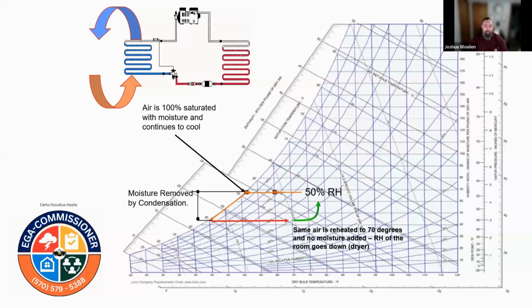And then what I did here was show you the value of moisture removal by condensation during drying, and how it refers to the amount of water vapor converted into a liquid and subsequently removed from that environment. This process is crucial in structural drying, as it helps to reduce the overall moisture content in the building materials, preventing issues like we discussed: wood damage, mold growth, bacteria, malodors and stuff like that.